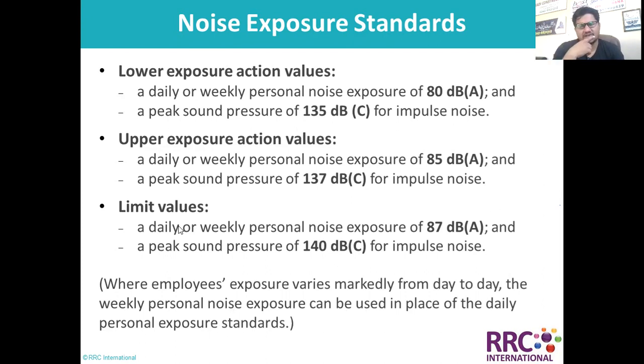There is a TLV register, a threshold limit value or time weighted average register, that we keep for each employee, especially for H2S. If one employee is exposed to H2S, we will keep putting in the record, say 2 hours today, 3 hours tomorrow, date-wise. Ultimately we will get weekly numbers, and we make sure they are not exceeding the legal limits. It's not like one day you are exposed to H2S for 8 hours, and the next day for 6 hours. Make sure the cumulative numbers are also not exceeding the limits on a weekly basis as per legal requirements.